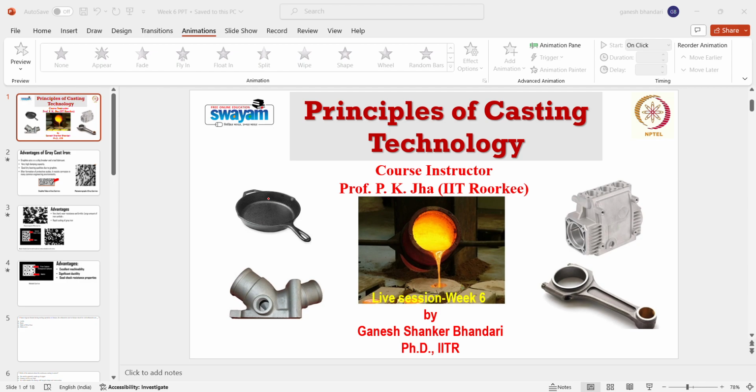These two phases are generally known as stable phases in the iron carbide system. Other phases are known as metastable phases, because according to temperature they are going to be converted into other things, and that also depends on your process kinetics. If you are going with an annealing process, a martempering process or an austempering process, that will also depend on what type of phases the metastable phase is going to convert into.